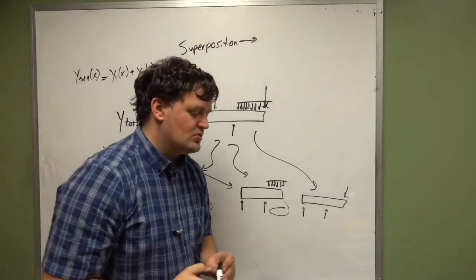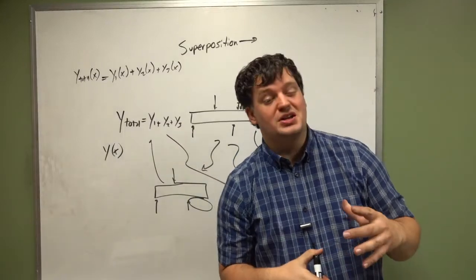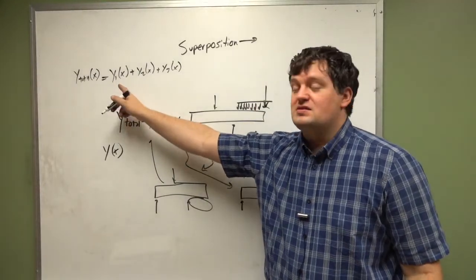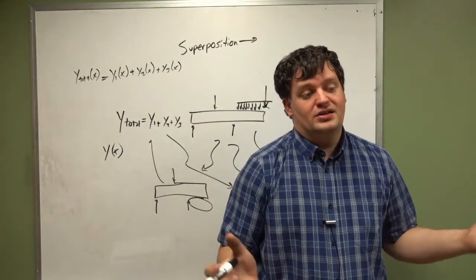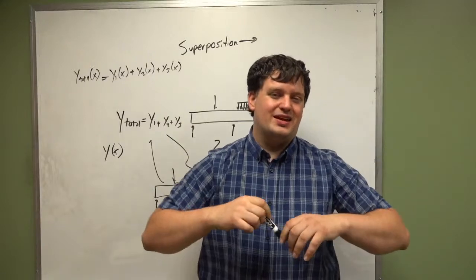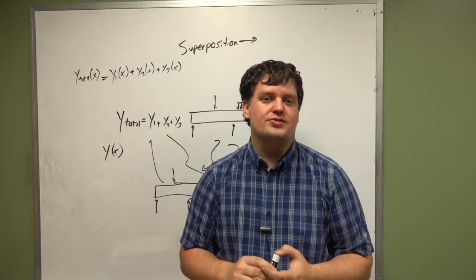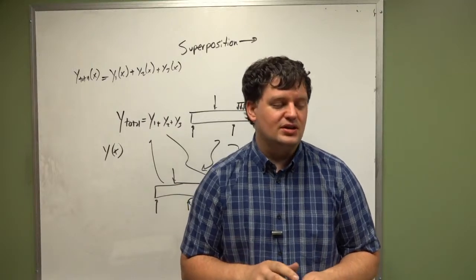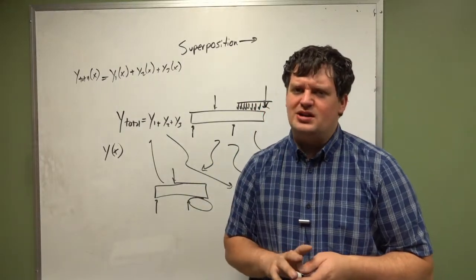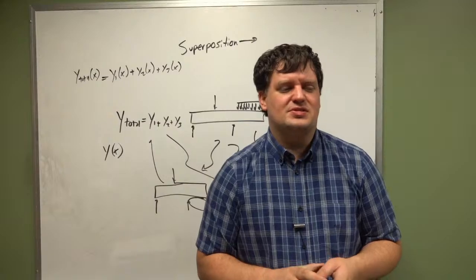Now superposition doesn't always work perfectly. In the real world, superposition doesn't quite operate the same way, because deformations here will cause the loading conditions here to change. You're no longer pushing vertically, etc. So superposition has its applications, and it is something that you need to know for these homework problems that I'm going to give you next week. But in real life, this is why finite element analysis software is more highly trusted anymore than just doing hand calculations.